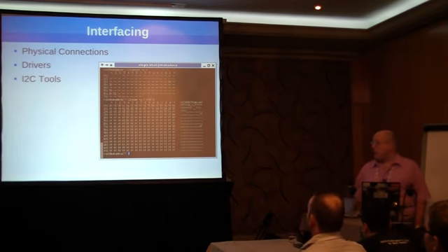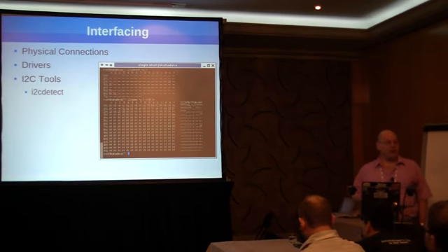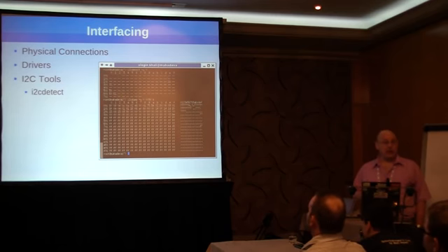That brings us to I2C Tools, and that's the exact name of the package, I2C Tools. It consists of a wide range of small little applications that use the I2C character device driver. The first one, and the one that most everybody can find very useful, is i2cdetect. You basically just give it the I2C bus number, and it will scan the bus and identify addresses that are on the bus that have something available or are showing up and answering.